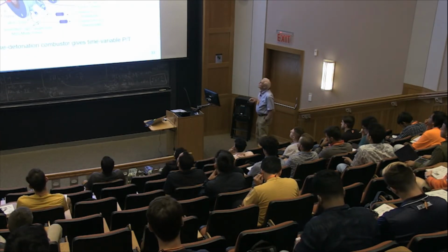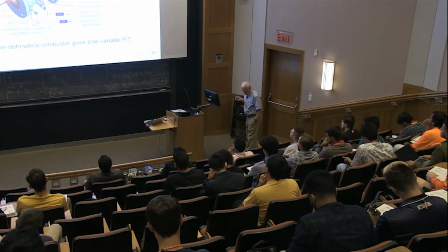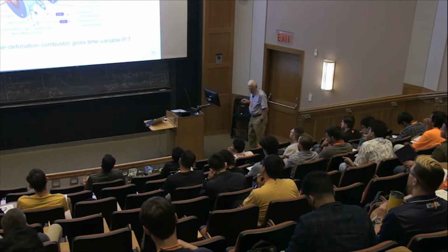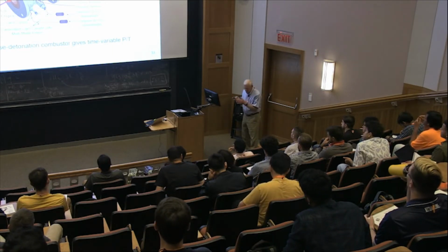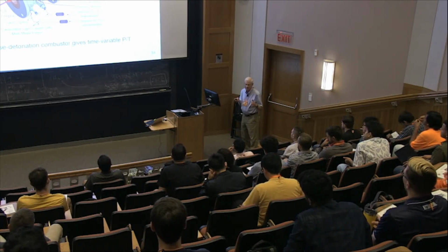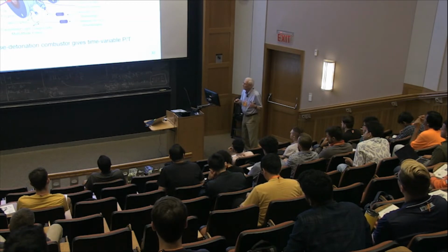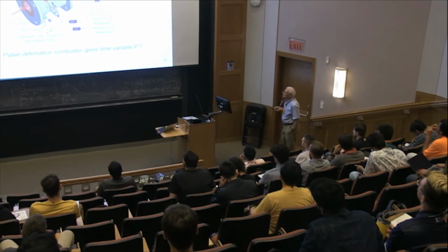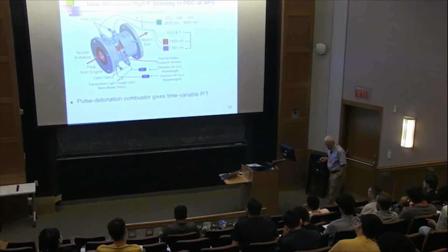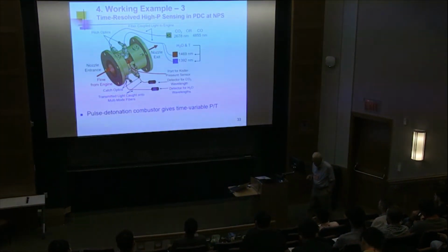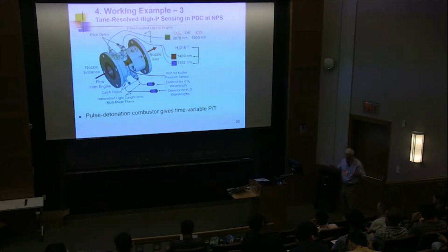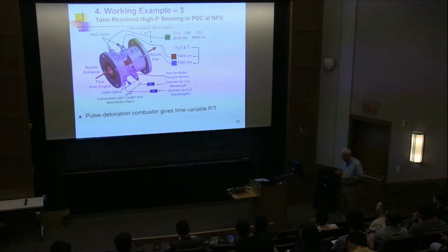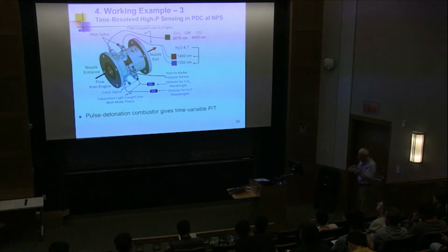Another interesting thing, this is maybe 10 years old. PDC stands for Pulse Detonation Combustor. In the early days, now people are using rotating detonation engines, but previously it was pulse detonation engines, PDEs. So this was a pulse detonation engine. We have some colleagues 75 miles to the south, at the Naval Postgraduate School, and they have one of these systems. In a pulse detonation engine you fill it with something like ethylene and air, ignite it, the detonation wave comes down, and flows out a nozzle. You need to work it at higher pressure, so there's a throat.